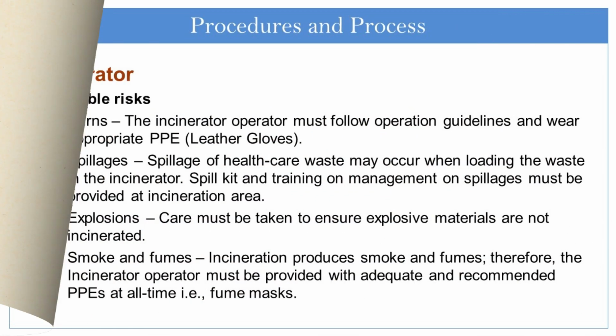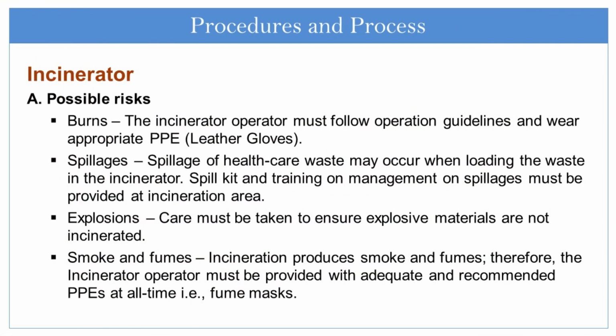So now let's move to the incinerator, how to operate an incinerator. First of all, again, safety first. Let's look at the possible risks. An incinerator can cause burns, spillages, explosions, smoke, and fumes. So to avoid burns, the incinerator operator must follow the operation guidelines and prepare appropriate PPEs. Here, he should use leather gloves.